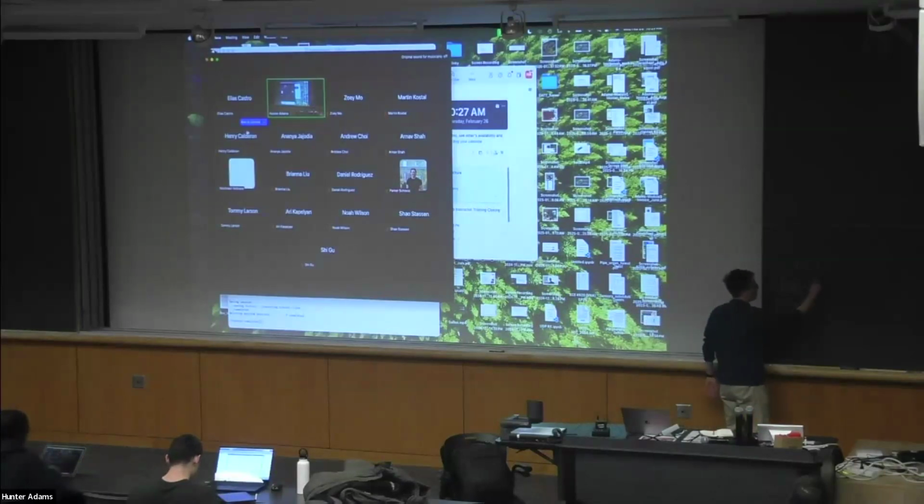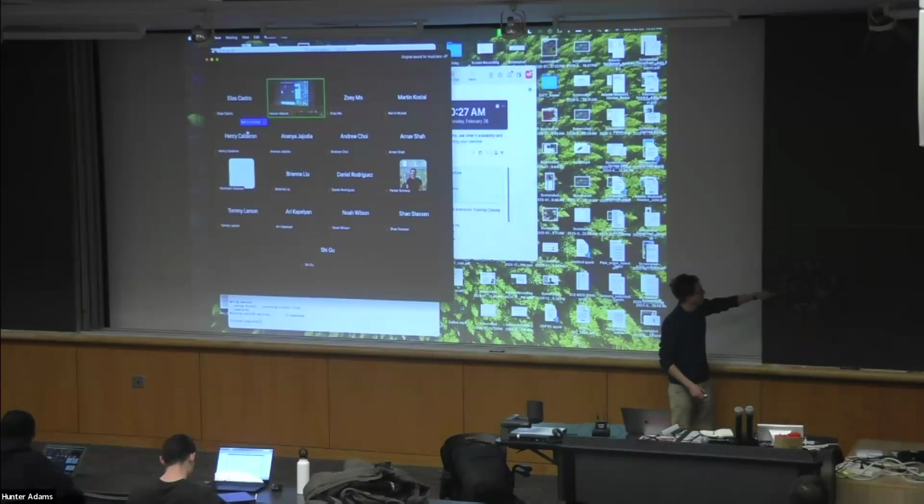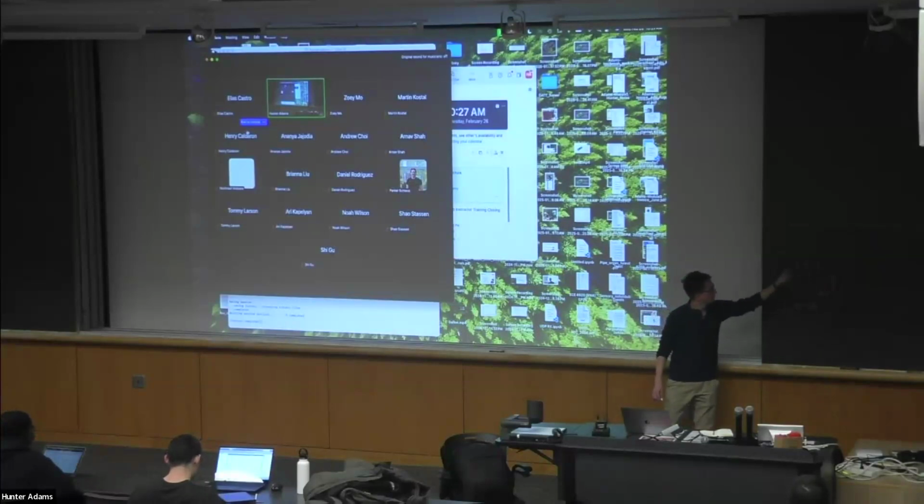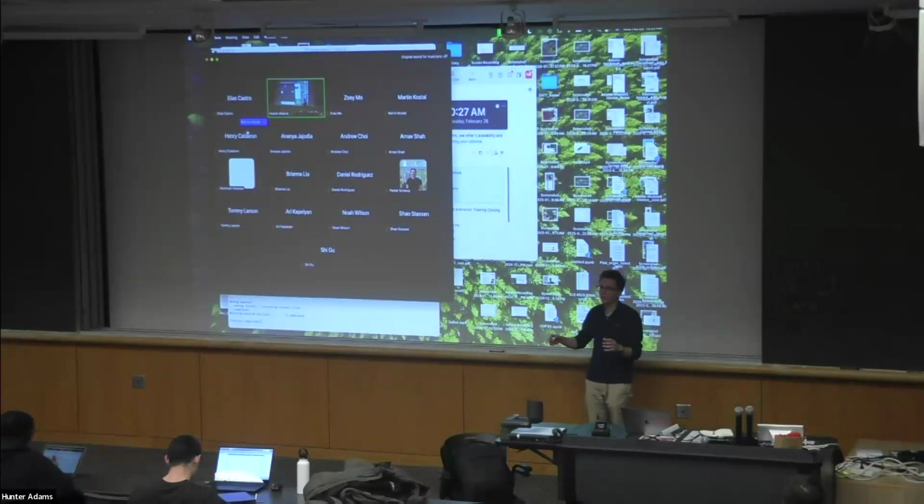The demo chains these two. The control channel rewrites the read address of the data channel and triggers it, starts it. The data channel produces a whole sine wave, goes through the full table, and then triggers the control channel to start again. They ping pong back and forth forever, which is why in the demo, what you hear coming out of the speakers is a persistent sine wave. You get one period, re-trigger, another period, re-trigger, and it's persistent. We don't want a persistent sine wave. We want a single period of a sine wave every time a ball strikes a peg.